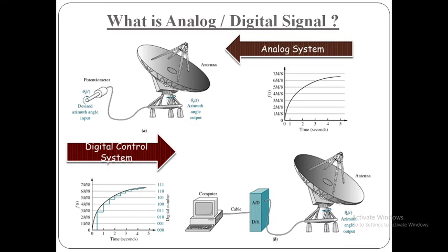Okay, so an analog signal is continuous and it is shown by a line. Here you can see this is the analog signal, shown by a continuous line, and it can vary in signal strength, meaning amplitude, and in frequency. The wave amplitude is the value of the higher and lower points of the wave, while the frequency is measured by the wave's physical length from left to right in one cycle. The sound from a human voice is analog because the sound waves are continuous. Also light waves are analog.